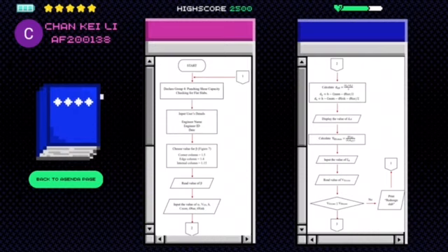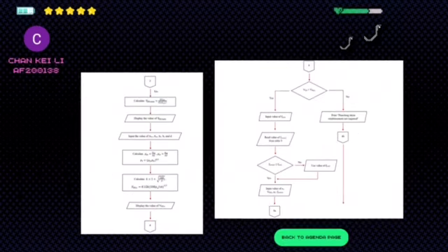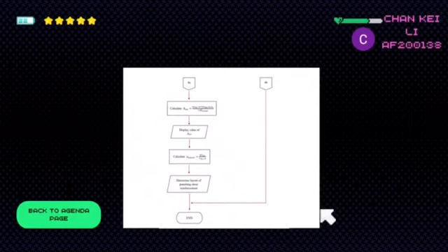When the VRD maximum is greater than the VED maximum, we will continue with the programming, else we will print redesign slab. Next, we will calculate the value of VED max and input all the relevant data such as ASY and ASZ to calculate VRDC. If VRDC is smaller than VED, then we will input the value of FYWD and FYWEF. If FYWD is greater than FYWDEF, then we will input the relevant data in the next step.